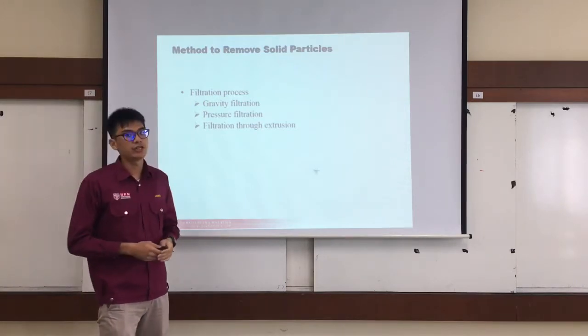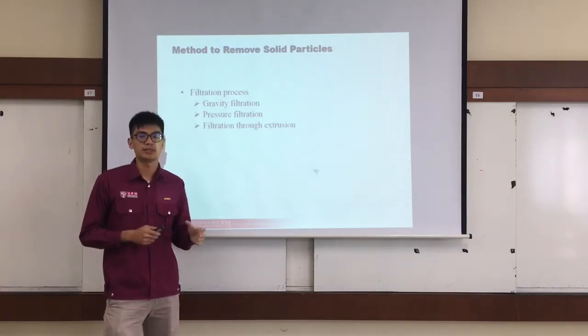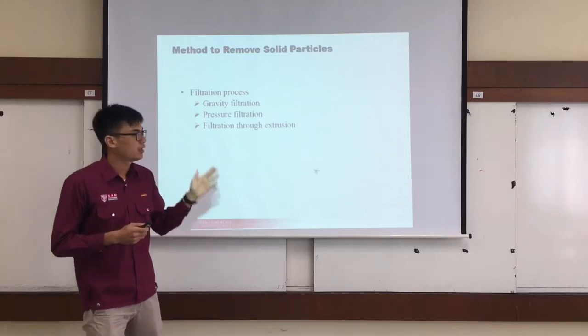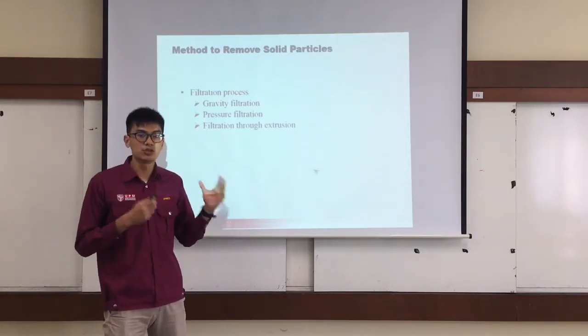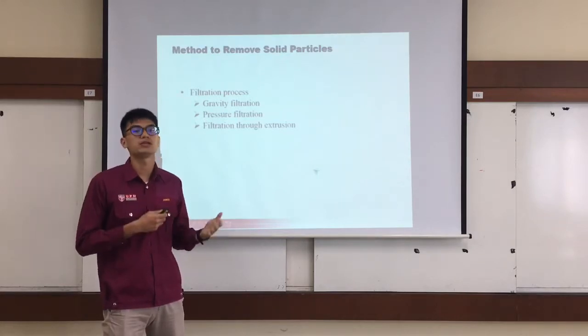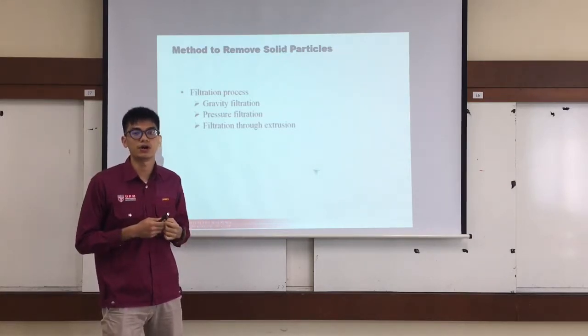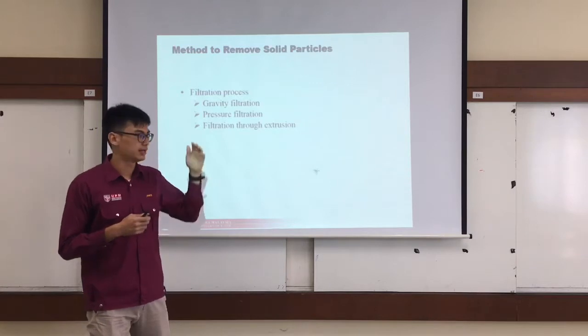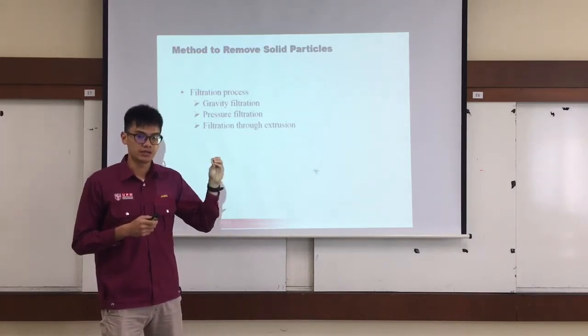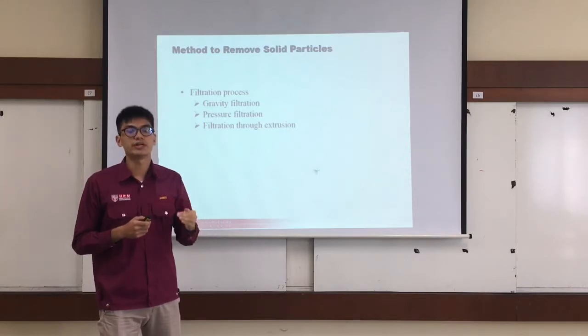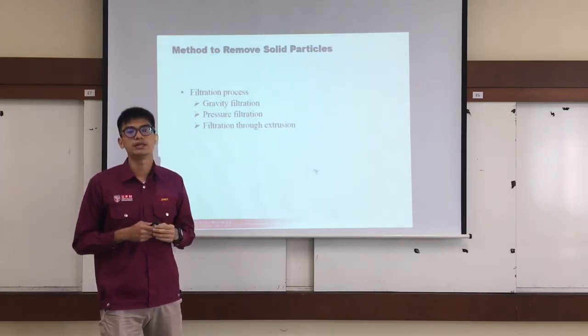By considering only the existence of solid particles in the oil, vegetable oil shows good property as compared to mineral oil. Hence, the higher viscosity level in vegetable oil leads to a slower rate of reduction in breakdown voltage as compared to the one in mineral oil.